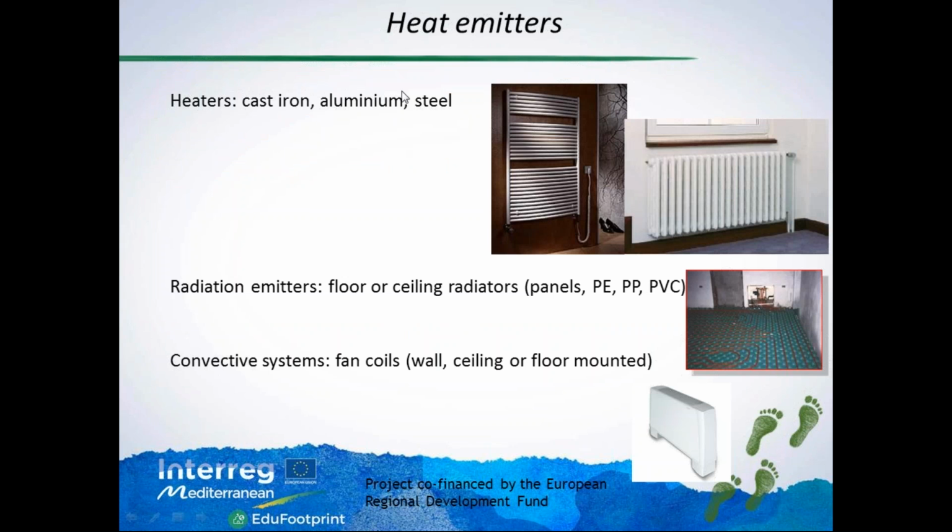We start from the end, and the heat emitters are mainly 3 types. We have heaters, so-called radiators, but the main physical effect used by them is convection. These are the very typical ones, and they come in different materials: cast iron, aluminum, steel.